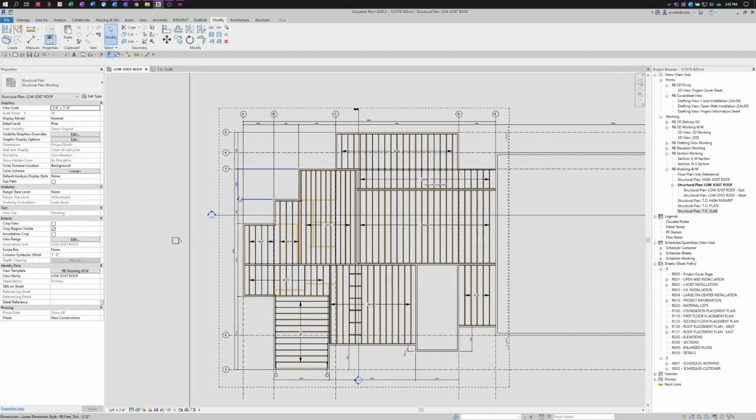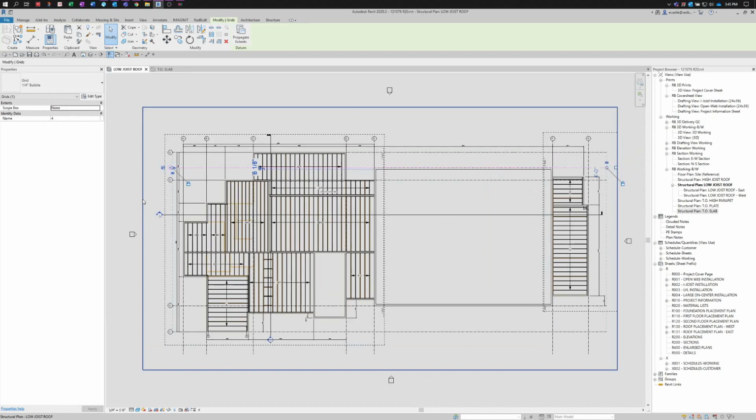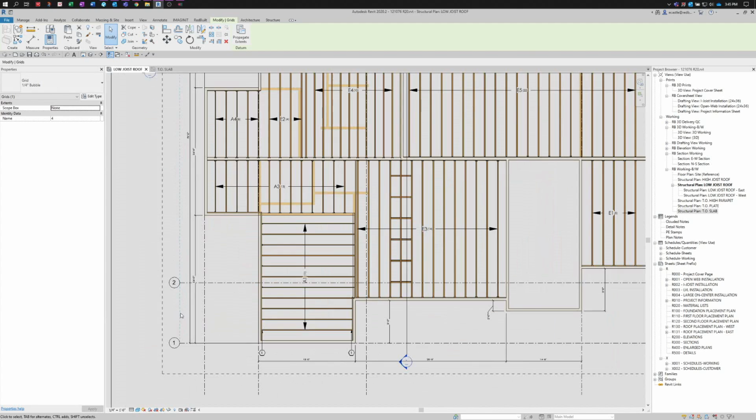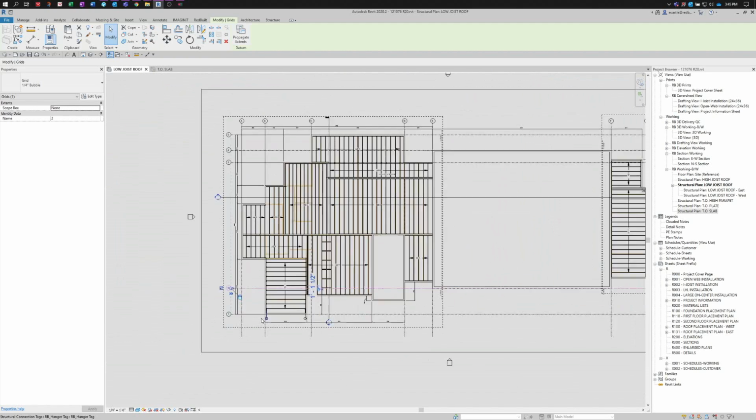Now I finished adding the existing dimensions I had and adjusting them to fit and look nice. I want to make some adjustments to my grid lines. You see they're still going clear across the building. Some here, like grid 2, is not necessary on the west side, but is used on the east side of the building.